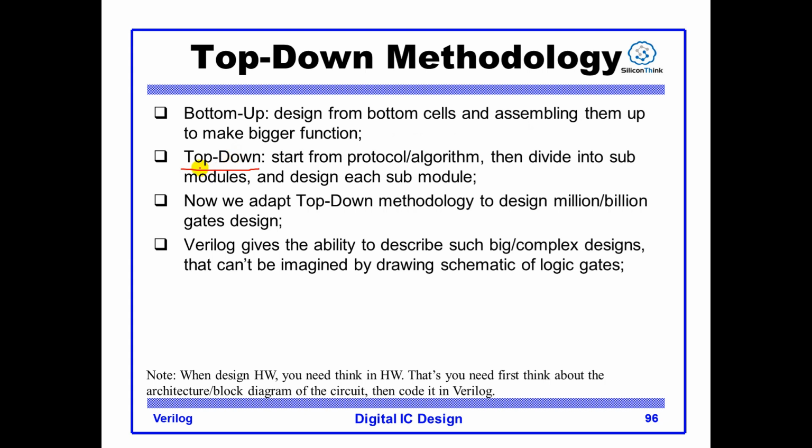While for top-down, we start from the protocol or algorithm, then we divide it into sub-modules, then we design each sub-module. And finally, we assemble the sub-modules up to make the big function.